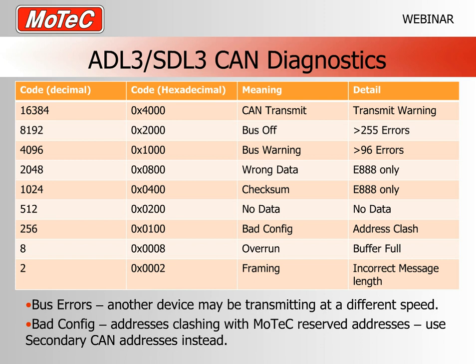If you are monitoring this CAN status, the one you will see almost always is error number 512, and that simply indicates that there's no CAN message coming into the system, so therefore your transmit device is not functional, or there is some other bus clash that's not working. Now, in most cases, if there's a bus clash, what that means is that there are multiple devices on the bus, or, for example, two devices running with two different data bus speeds. You'll get a clash which generally comes up with a different message. Normally the bus error message is the one that comes up.